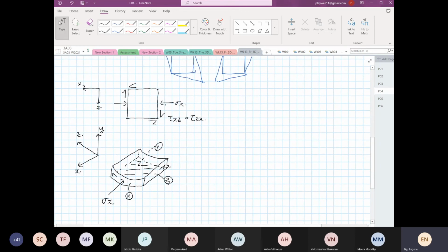So we know that stress Y is definitely equal to 0. There's no normal stress. So now we sketch Mohr's circle. Again, as I said, this is just a sketch. So normal stress, then we have our shearing stress, clockwise, anti-clockwise.